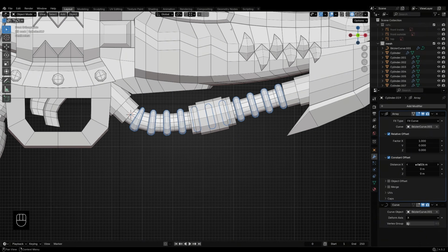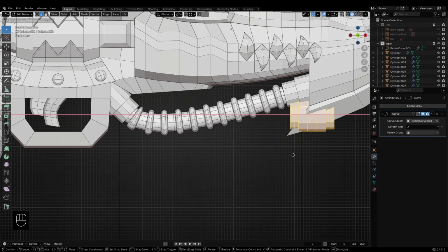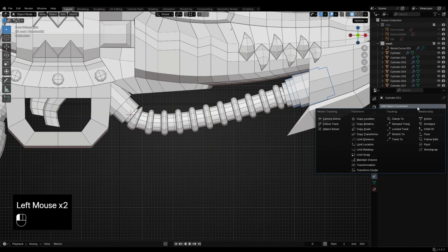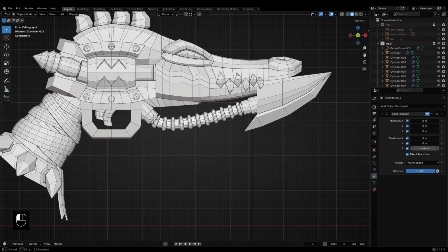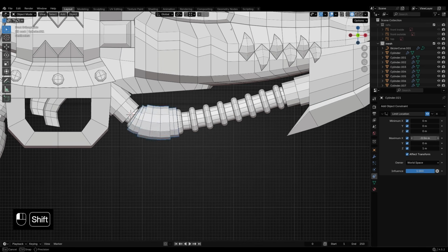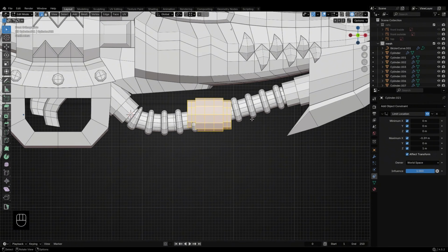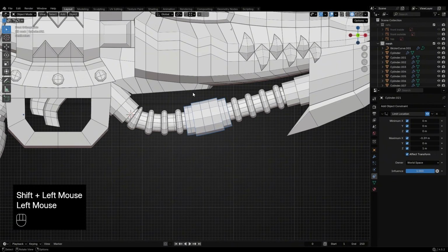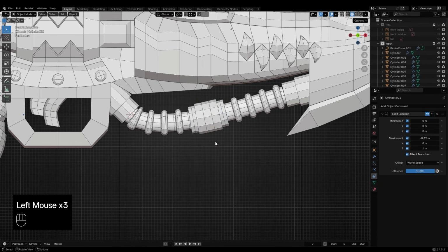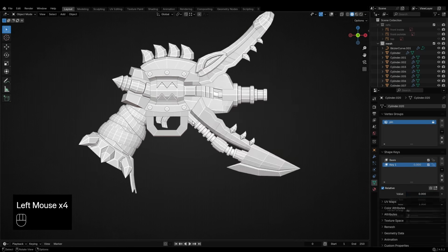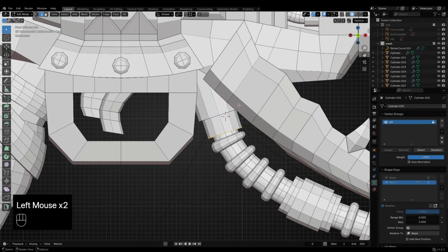Now let's try locking the position of this ornament mesh using a limit location constraint. Before that, align the orientation toward the end of the curve. Then add a limit location constraint. Enable all minimum and maximum options, and also enable effect transform. Adjust the maximum X and Z values, then fine-tune the position and scale of the ornament mesh. Next, review and fix anything that still feels off.